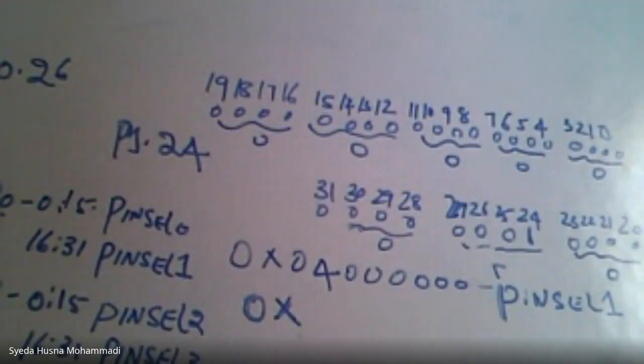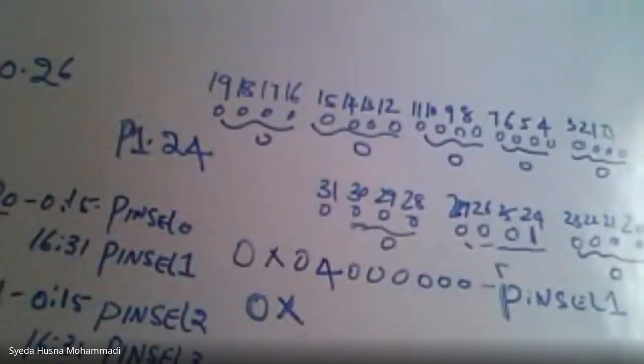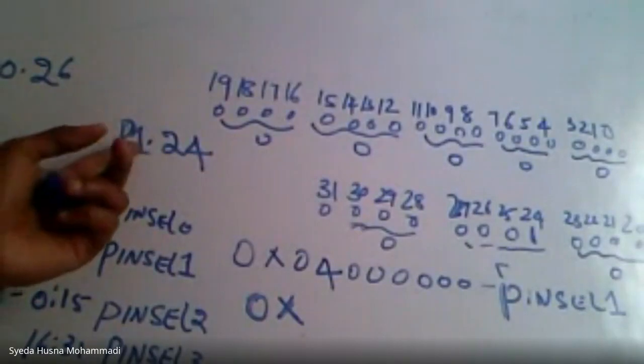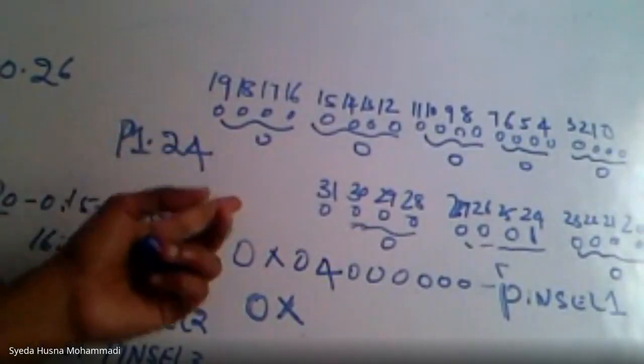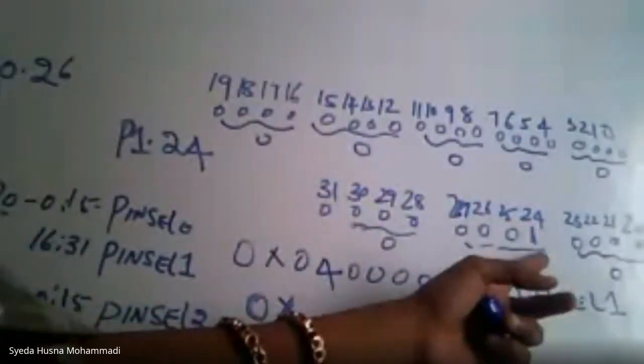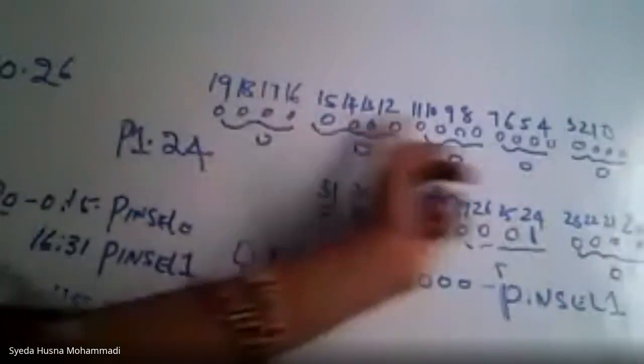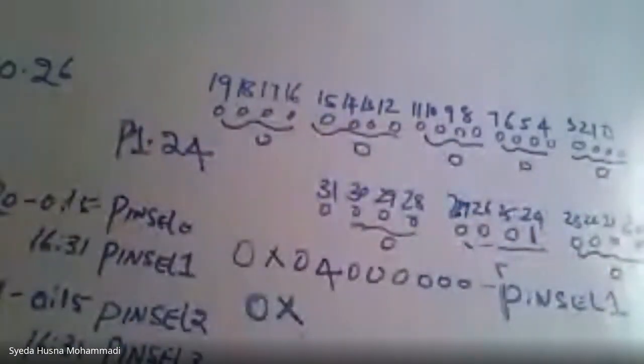What is the value you'll be generating here? I have to configure the DC motor in the direction of the output. Your DC motor is connected to port 1 pin number 24. So go to pin number 24 and place the value as 1, and the rest of all bit values as 0. What is the equivalent value I'm generating here?